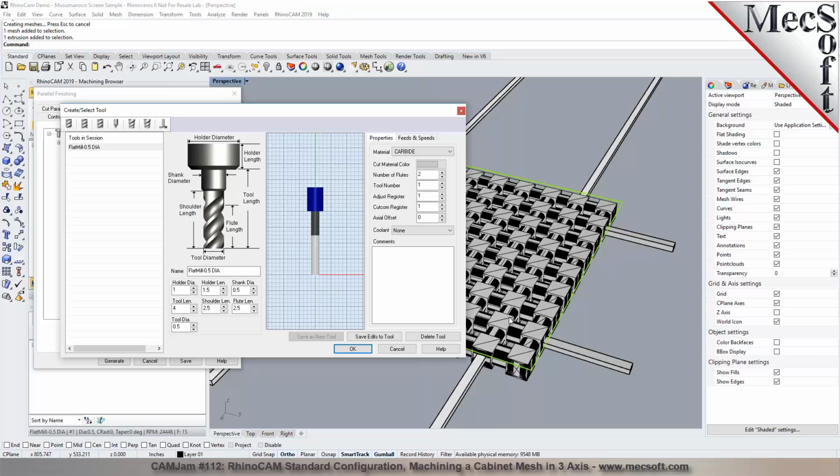Yep. So the only thing that you're going to see is a fillet radius in this corner, as the tool goes down and rolls over this radius. This is a flat area, and this is a vertical, so you're going to see a fillet there. That will depend on the diameter of your tool.